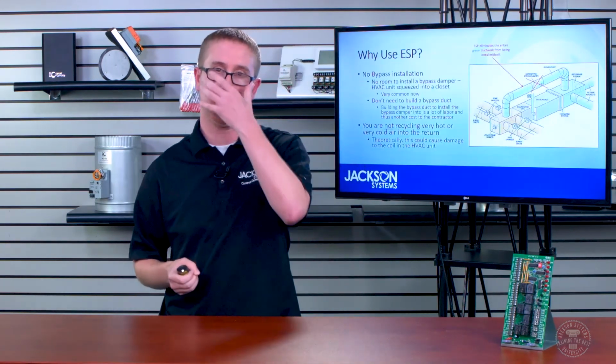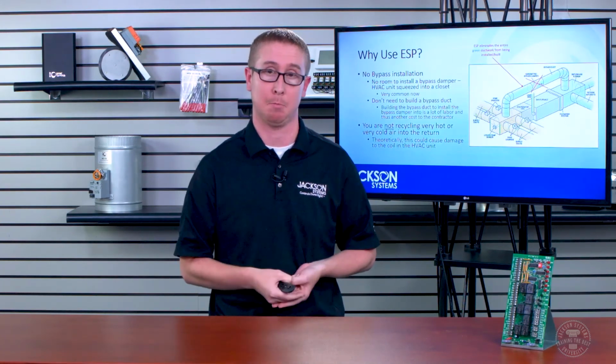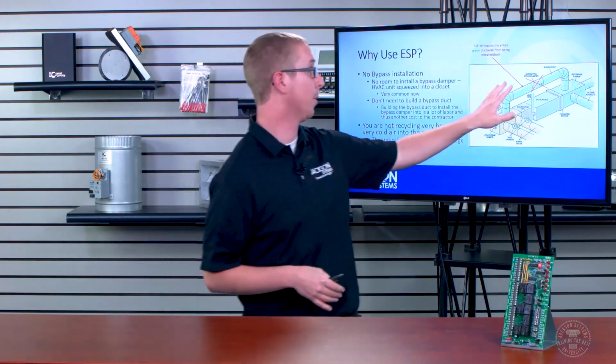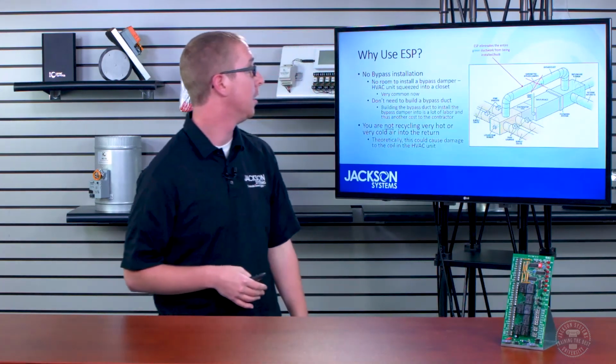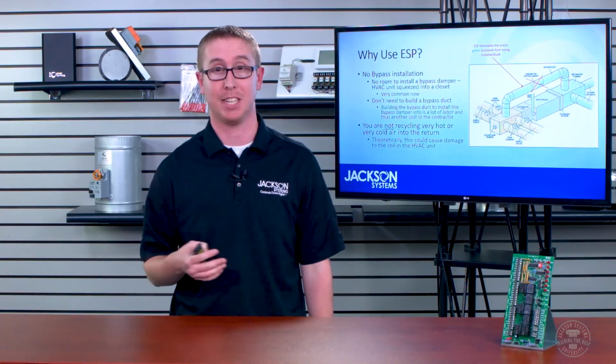Why do people use ESP? The biggest reason is whether the labor would just be a pain or it would be physically impossible, but they just really don't want to install this green ductwork here. It's expensive. A lot of the times, if the equipment is in a very small closet, it's impossible.